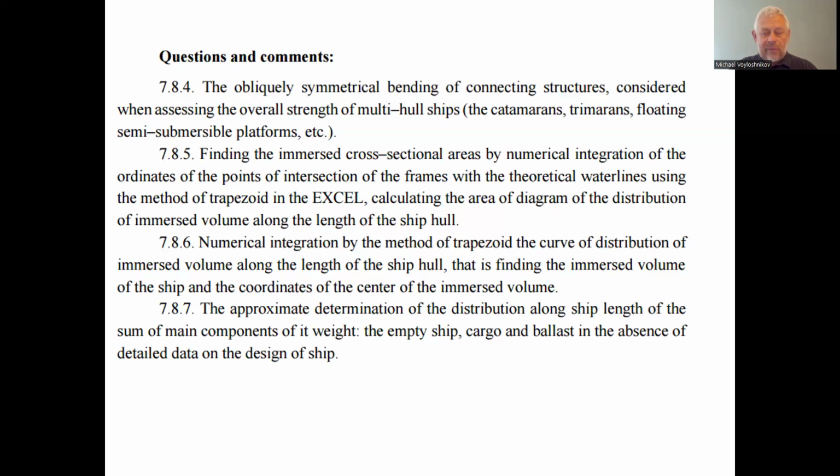And as well, we have to adopt an adjustment for the extreme submerged areas, for transverse frame 0 and for transverse frame 20. We apply the adjustment to the final result of the total in accordance with the trapezoid method. And besides, we have to multiply that by the theoretical spacing, the distance between each two theoretical frames, transverse sections.